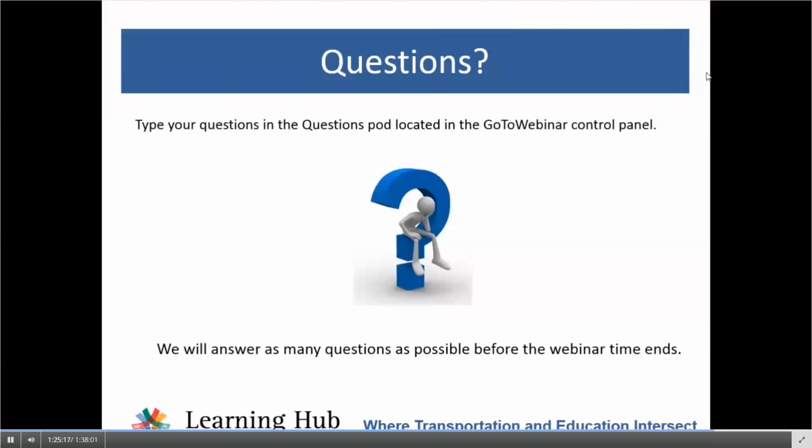How is EDTT accounted for or reflected in the LOS results for alternative intersections? Yeah, so the EDTT, or extra distance travel time, is added to the control delay. So let's say a movement experiences 30 seconds of control delay and 10 seconds of out of direction travel time, then 30 plus 10 gives 40 seconds of experienced travel time, or ETT, and that's the one that's used in the level of service lookup table.